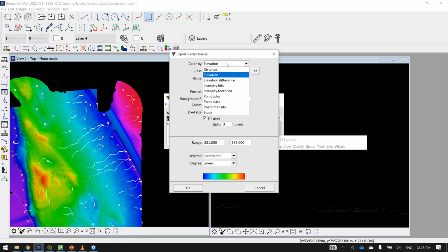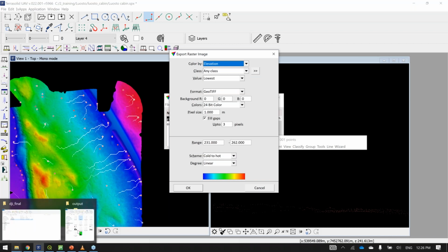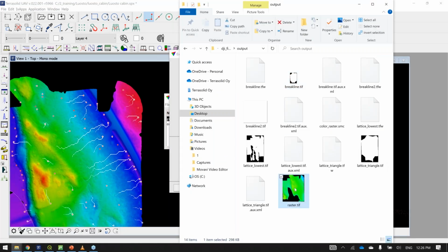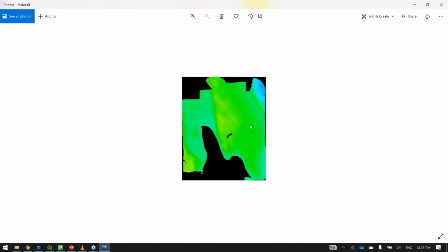In this case, you can also choose what kind of value will be written in the file: the XY coordinates of the point, and then additionally the value. Just in this case, not the value will be written, but the color according to the value. And then as an export file, you would have a TIF file already colorized.